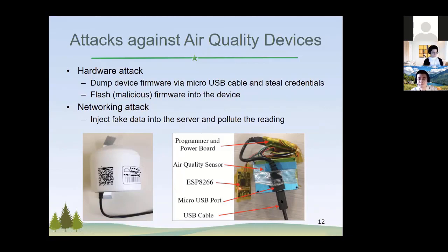But really, what happens is they don't have any hardware security. We can just hook a normal smartphone micro USB cable to this micro USB cable port here. Then we can read anything on the flash, including users' password, Wi-Fi credentials, anything you store within the flash of this device. And also we can flash our own software firmware onto this device. So it means if you buy their device, I go to your home, I just hook a cable to the micro USB port because you put it outside, right? Then I can just change anything. And so that's the problem.